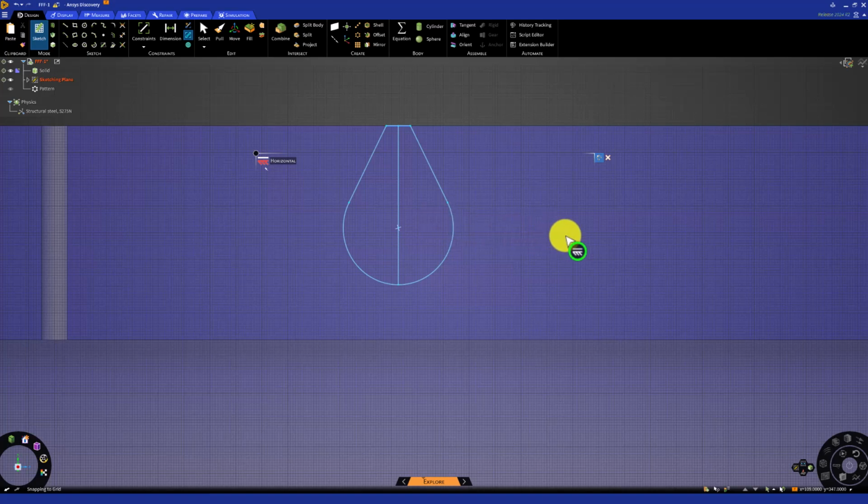If this does not have the desired effect, your sketch may be oriented differently than mine relative to the coordinate axes, and using the vertical constraint tool will work instead. With this complete, click Escape to exit the tool.